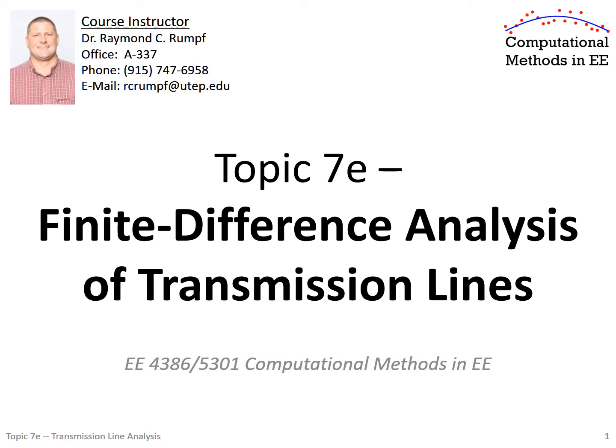Another property that we'll analyze is the effective refractive index. Refractive index is the factor by which a wave slows down relative to an electromagnetic wave in outer space. So the higher this effective refractive index, clearly the more interaction the electromagnetic fields are having on the line, and they're traveling slower.